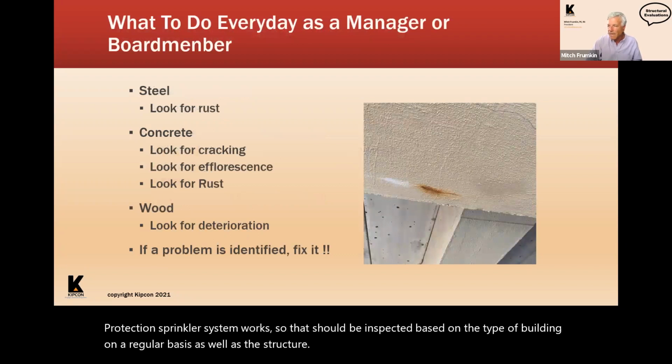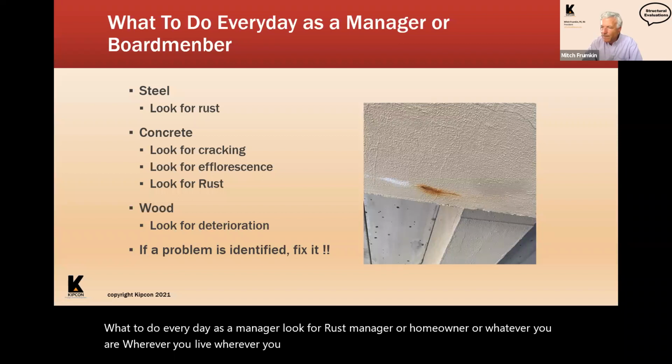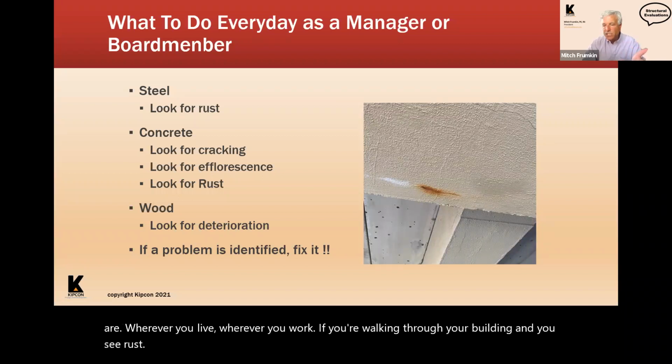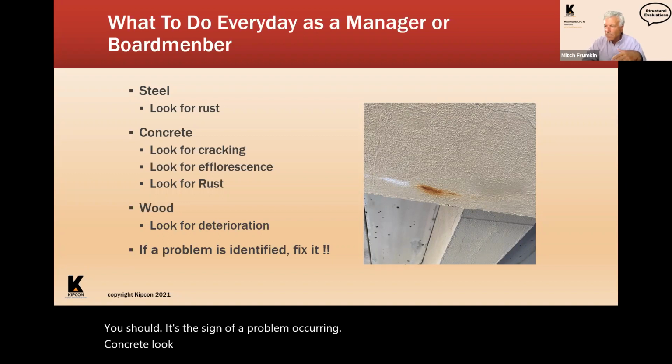What to do every day as a manager? Look for rust. Manager or homeowner, whatever you are, wherever you live, wherever you work, if you're walking through your building and you see rust, it's the sign of a problem occurring. Concrete, look for cracking, look for the efflorescence, look for rust.